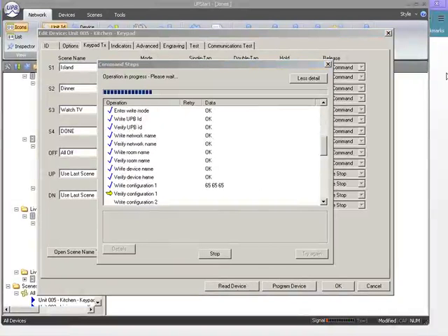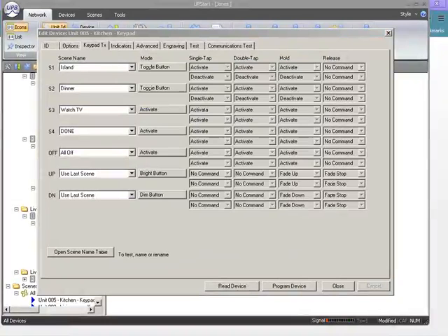Another question came up as we're programming, or it's a comment: you are setting landscape lights to 90%. Obviously, I do not want to do that if I've got an AM12, and that is correct because an appliance module will not dim. And the receptacle module that we have coming will not dim either. It is just an appliance module.